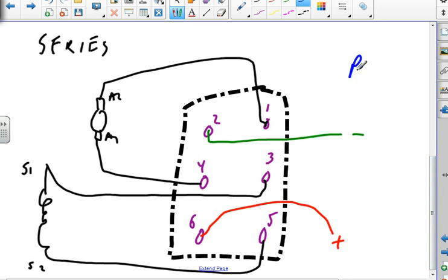Now I'm going to look at the reverse direction. Reverse direction says I have to hook up that guy, and this guy. So I come into S2, but then I go S1 to A1, and then I go A1 back out. So I've switched the polarity of the armature, making me go in reverse. Okay. How wonderful is that? Okay, one more set of pictures.